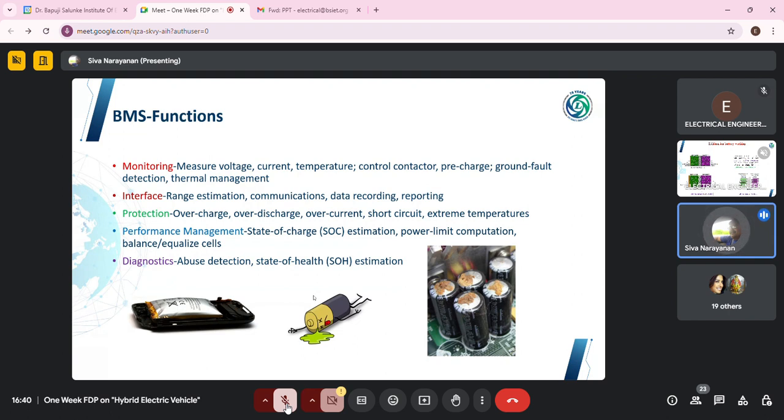In most vehicles you have this reporting. It says how much distance we traveled on the last trip, what SOC was used on the last trip, when our last charge was, when we had 100% SOC, and when we achieved very good economy. All these are reports which are generated. To do that, we should develop some algorithm in the background. The next one is protection.